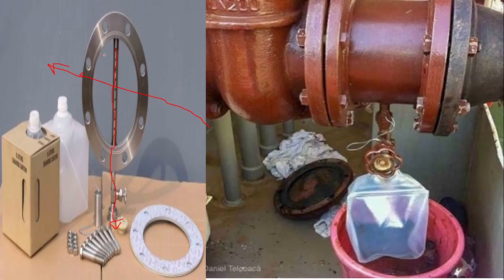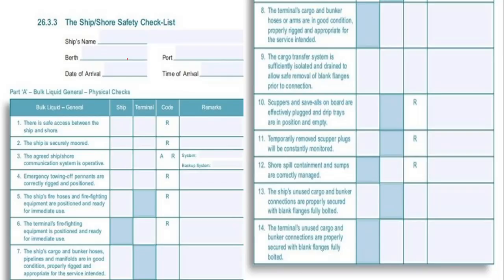So basically, drip by drip we will collect the sample throughout the bunkering, so that we can make sure what type of fuel we are receiving, and we can send it to the sample analysis lab to verify. Now there is a ship-to-ship checklist which you need to complete before putting two ships together, to ensure that all the rules and regulations have been followed.